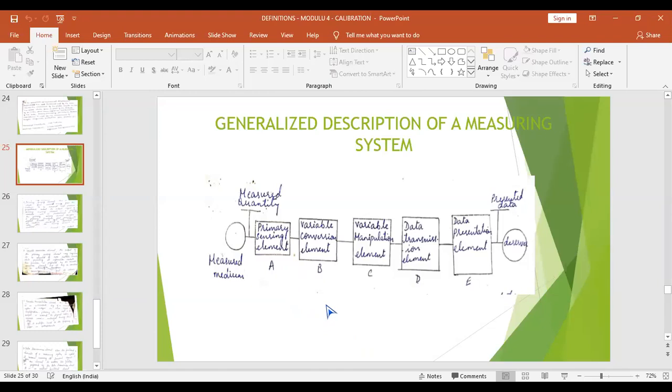Here you have to measure the voltage coming from the circuit. Before starting this experiment, what you have to do is bring the strain indicator to read zero, or null balance. Then apply the load on the cantilever beam.